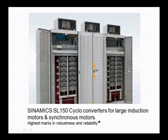This power rating is up to 36 megawatts, and it scores highest marks in robustness and reliability. These converters are used for large induction motors and synchronous motors of large power rating. The power rating here is 36 megawatts, but the range is 0 to 150 megawatts. You can use cycloconverters at very high powers.